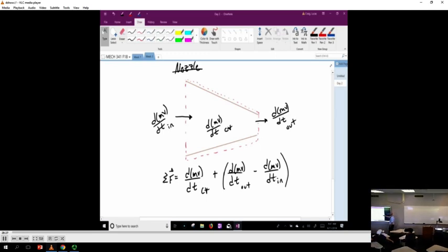So here's this nozzle. Here's our dotted lines. Coming in, our control volume, which is labeled CV, that's what we call it, you have all that momentum coming in. Out of this, you have momentum going out. And then you have change of momentum inside your control volume. The easier way to look at this is, what is dm over dt?